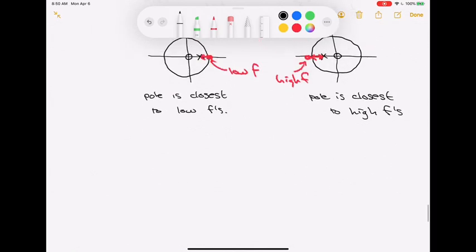If I was just going to guess, very quickly, something like a frequency response for this first system, I'd go minus pi to pi. I only have to cover the fundamental frequency range because it's a 2 pi periodic function. The same thing would be true for my second one. I would expect in this first one to have a higher gain near low frequencies than near high frequencies.